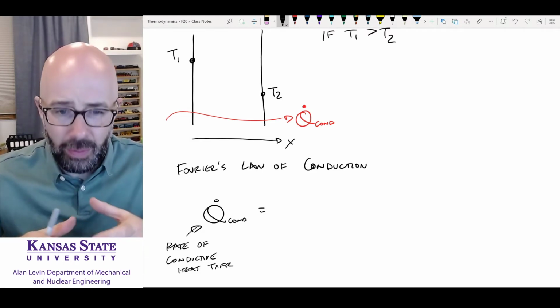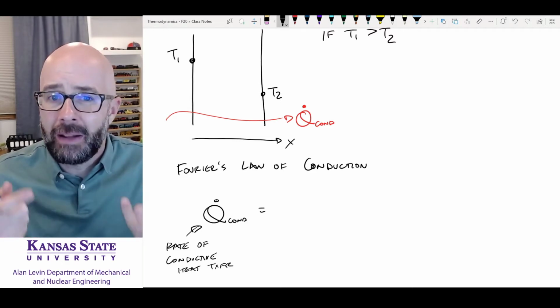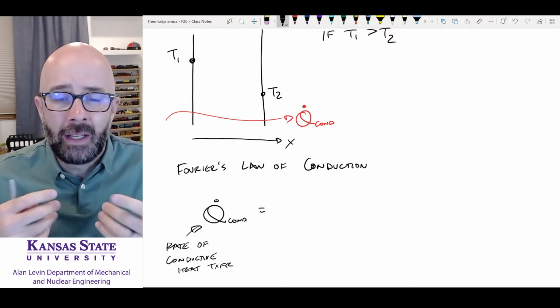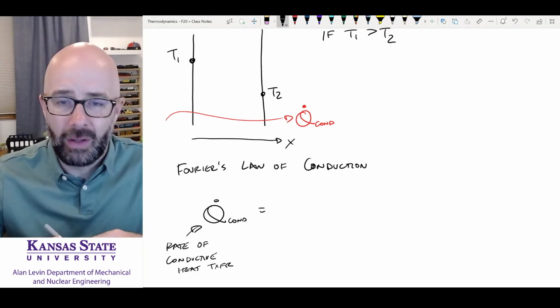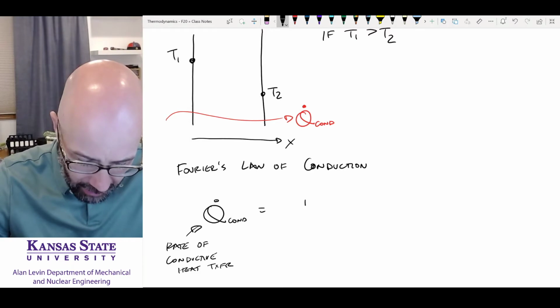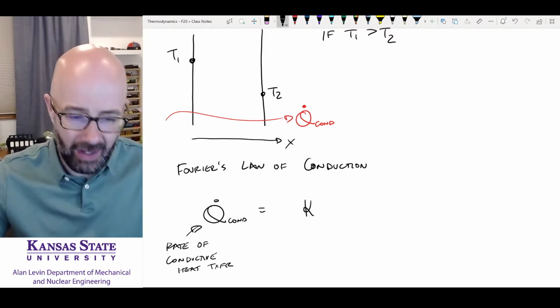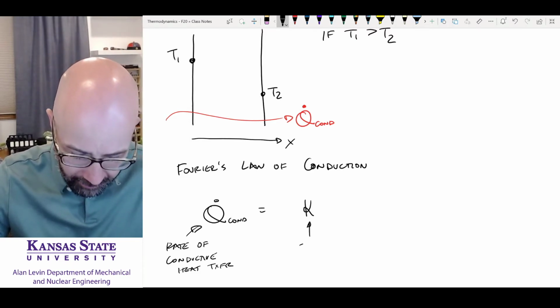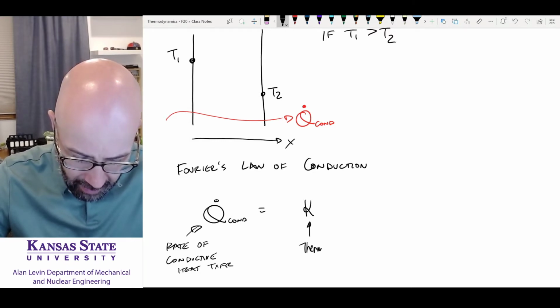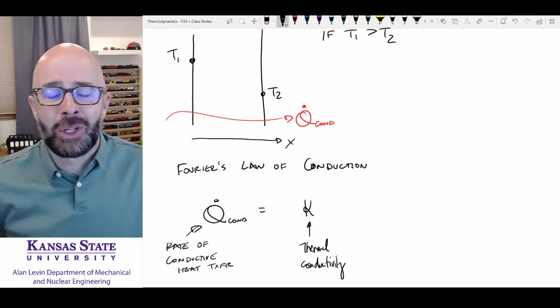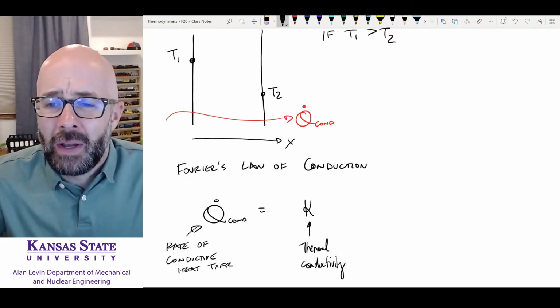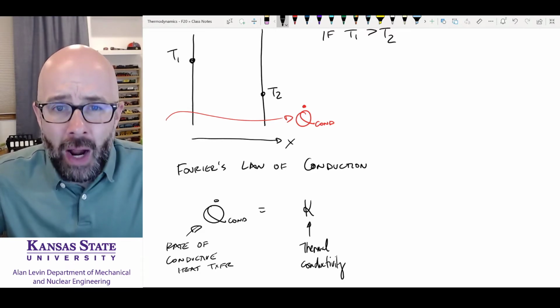So we had those two plates, and we knew that one was made of metal and one was made of a plastic or a wood. So the material property had something to do with the rate of heat transfer. And so there is something called k, and I'm going to make a fancy k here, called the thermal conductivity. It's easy to remember because "thermal conductivity" doesn't have a k in it, so we're going to use k for thermal conductivity. Thermal conductivity is a property.